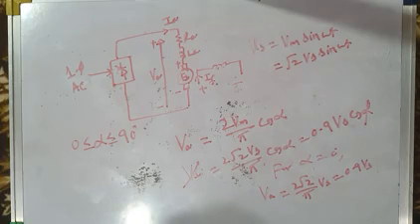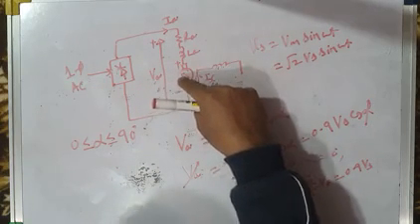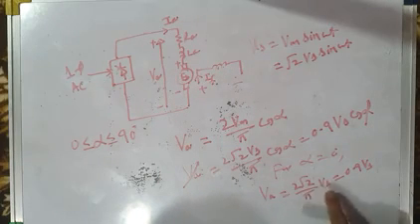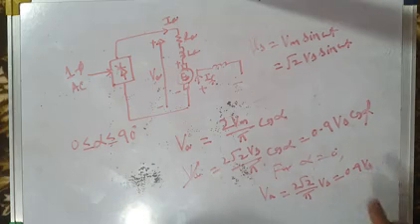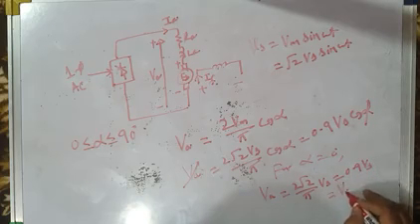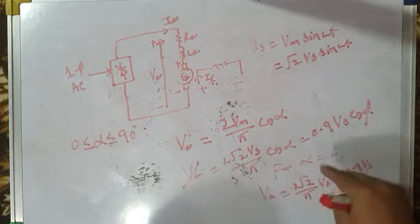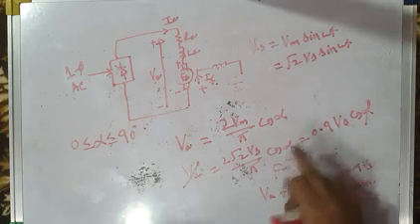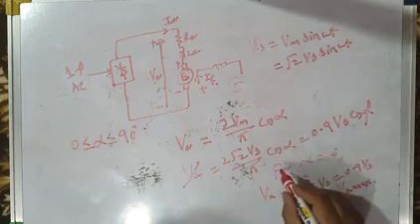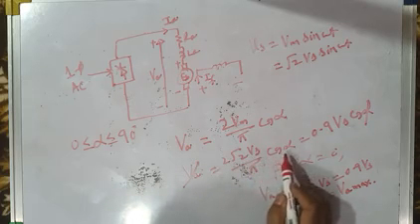When you select a motor, you already know the rated armature voltage of the motor. For alpha equal to 0 degree, your converter should produce the rated voltage of the motor, Va max. Then as you increase alpha above 0 degree, cos alpha decreases, and the average output voltage decreases